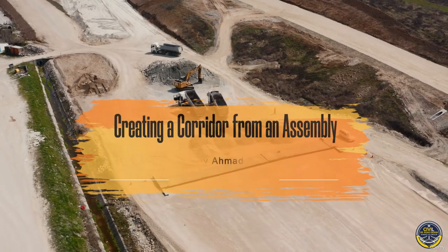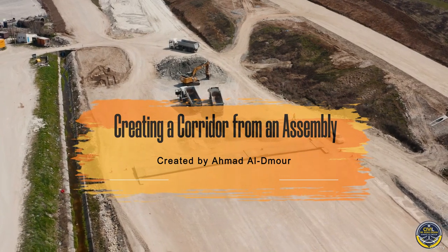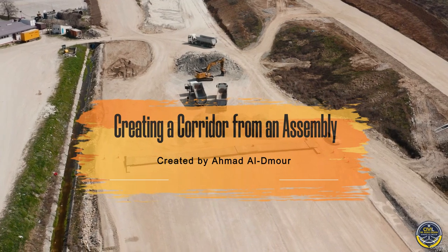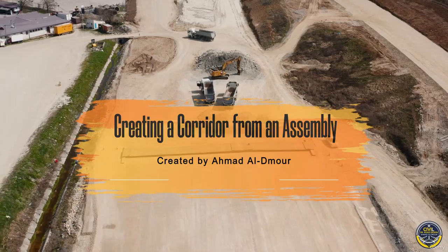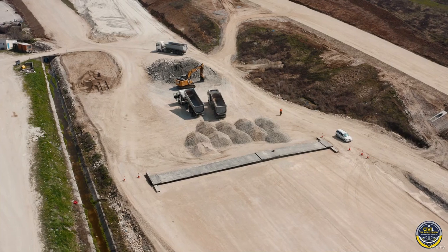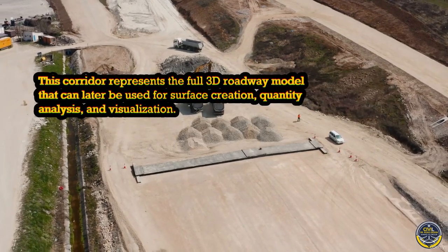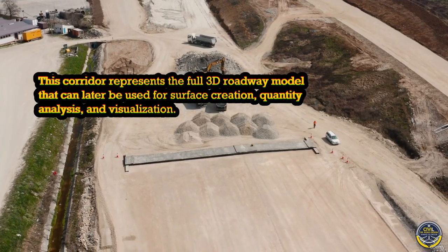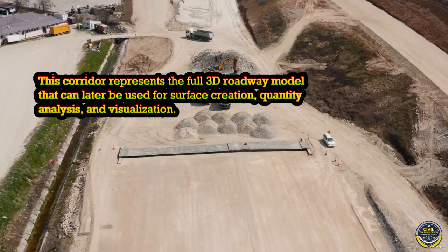Creating a corridor from an assembly. Welcome back. In the previous lesson, we built a complete assembly, a two-lane urban road with curbs, shoulders, and daylight slopes. Now, we will bring everything together and create a 3D corridor model. In this lesson, we will learn how to combine an alignment, profile, and assembly to generate a corridor. This corridor represents the full 3D roadway model that can later be used for surface creation, quantity analysis, and visualization.